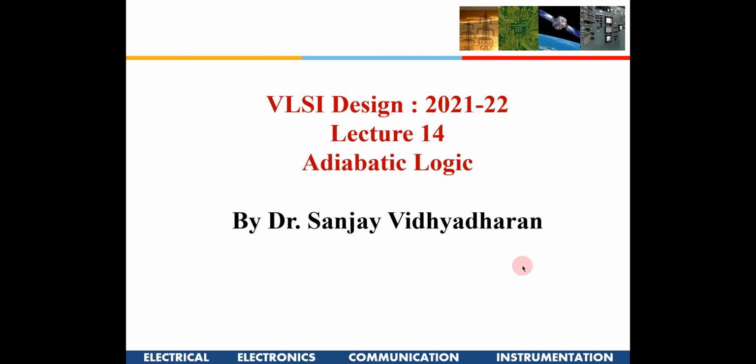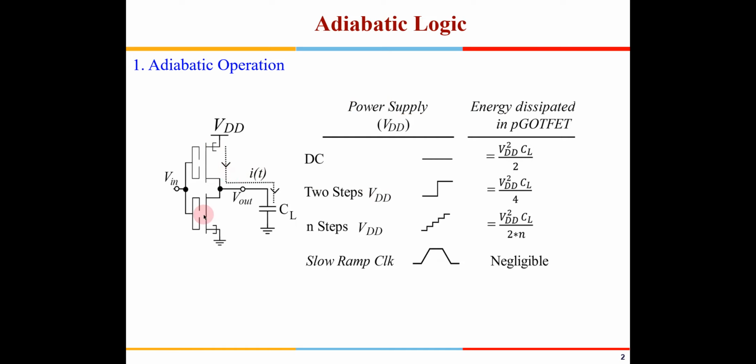Similarly, for many IoT sensors, and there are several applications, power is a major issue, whereas frequency is not an issue. So in those cases we use adiabatic logic. So what is an adiabatic logic? Suppose this is a static inverter. Just consider this as an NMOS and PMOS, although TFETs have been shown here. So just consider this as an inverter.